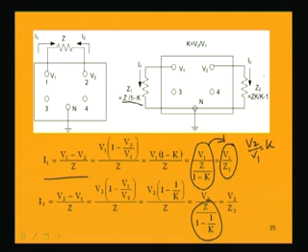So, from this figure we are proceeding, and finally, we are getting a circuit having the input and output sides separated out with respect to ground, but here it was having a shunted impedance in between the two nodes. Now, this theorem will be applied to our amplifier for distributing the capacitance between base and collector and separating out the input and output side circuits. So, let us do that now.